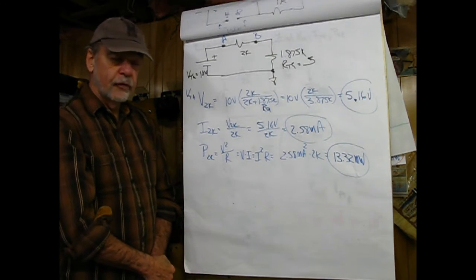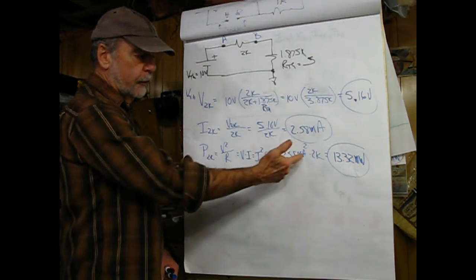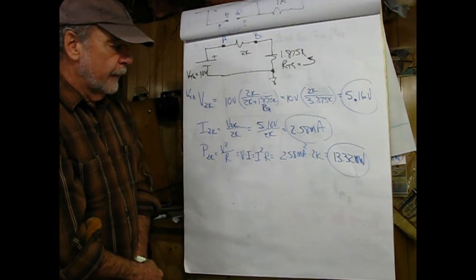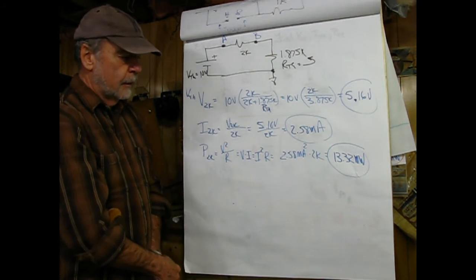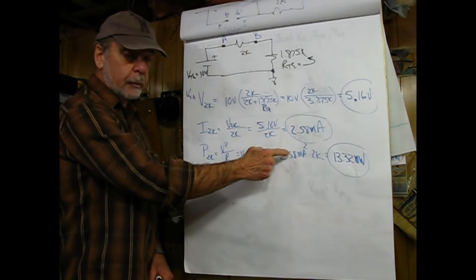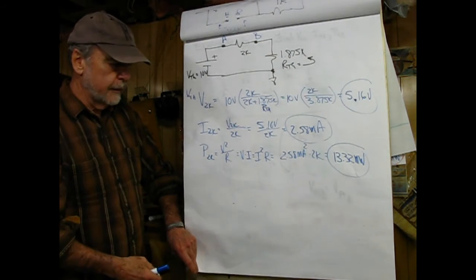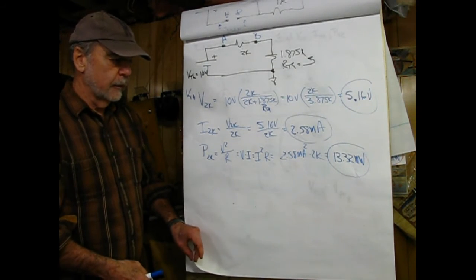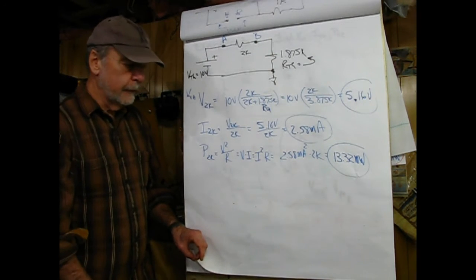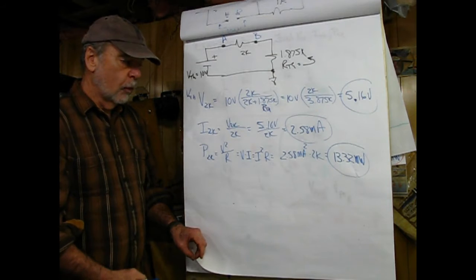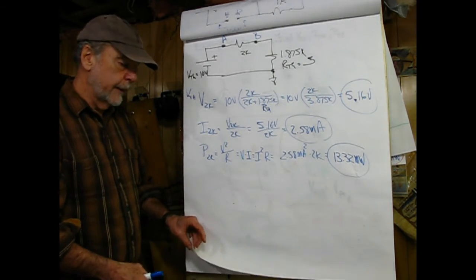What I chose in this example is I squared times R, and that comes out to be 13.32 milliwatts. Now remember, this is in milliamperes, so be careful when you square that. Don't guess on units in that case. Actually put it in your calculator as 2.58 e to the negative 3, or 0.00258, and then square that.